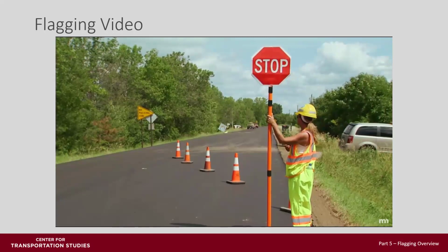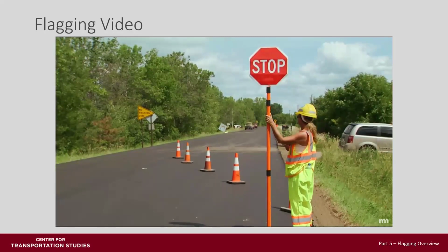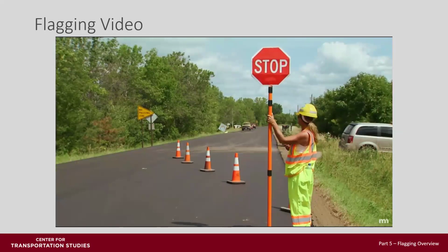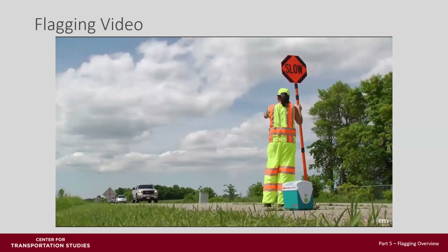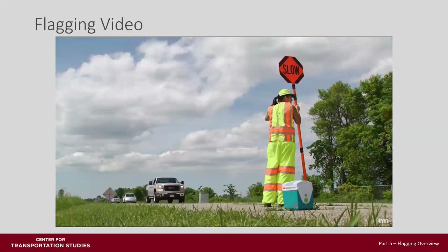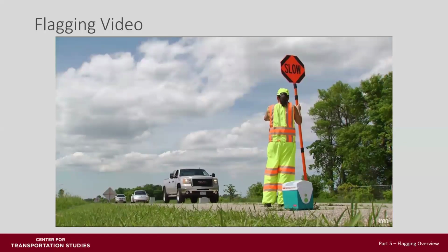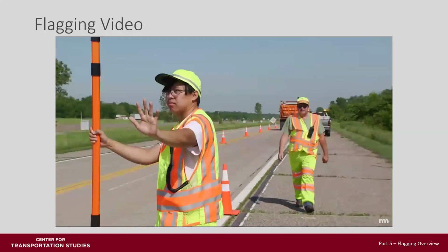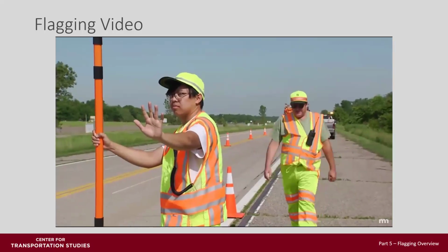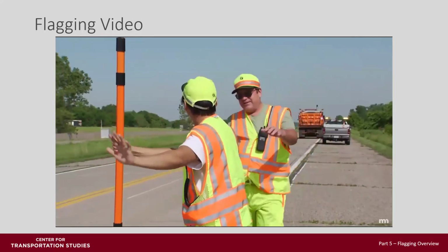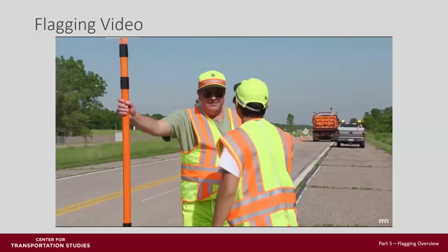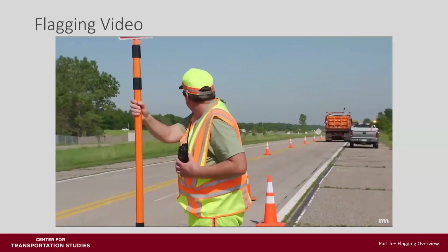Avoid standing where the sun is behind you and avoid standing in the shadows obscuring you from approaching drivers. Allow yourself an emergency escape route away from the path of errant vehicles. Make sure you're visible to oncoming traffic by standing alone away from other workers and worked vehicles. Any relief person must be properly attired with clothing that meets the ANSI requirements.